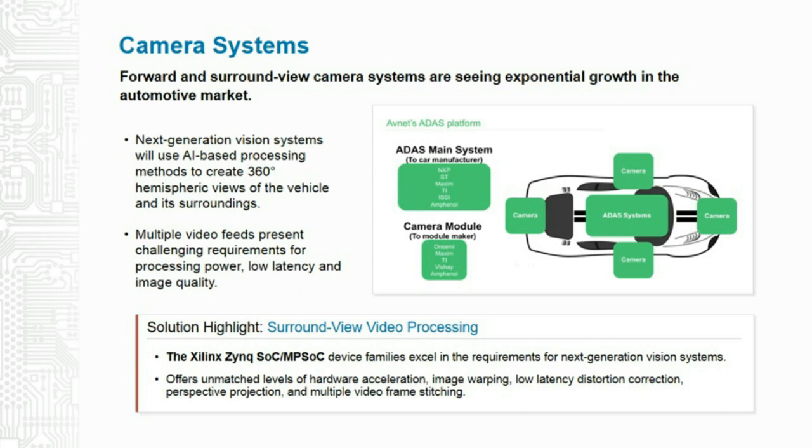A little bit later in today's presentation, I'm going to be spending a bit of time talking about sensor fusion. What sensor fusion is essentially is taking the input from radar and LiDAR and ultrasonics and cameras and combining them, using one to check against the other, so that if you're getting a report from one sensor that there may be an object out there, you want to confirm that fact with a backup sensor of a different kind. But I'll talk a little bit more about that momentarily.